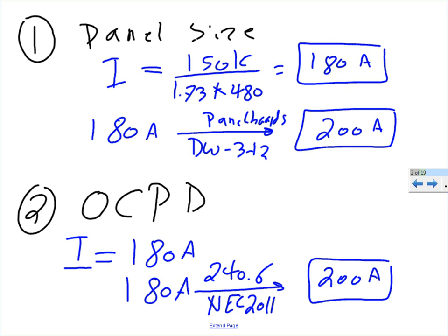You know, we have 175, and what the current listing that we are having is 180. Go up. I understand. What is the implication if you go down? Because I think this one is very important. Oh, very good point. Why can't I go down? I have 175. Should I go to 200? I can go down to 175, so I'm down by 5 amps, or up to 200, and I'm up by 20 amps.